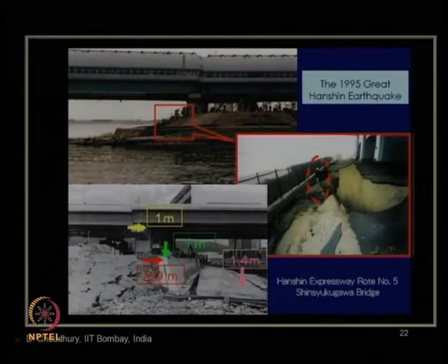After the liquefaction, what happens? The soil is no longer a solid material, but behaves like a fluid or watery material. So, obviously, they start flowing from a higher slope to a lower slope, that is higher gradient to lower gradient. So, once they flow out or move out from that place, obviously, the entire structure that was constructed on it starts moving or collapsing, and that collapse can be both in vertical direction as well as in horizontal direction.